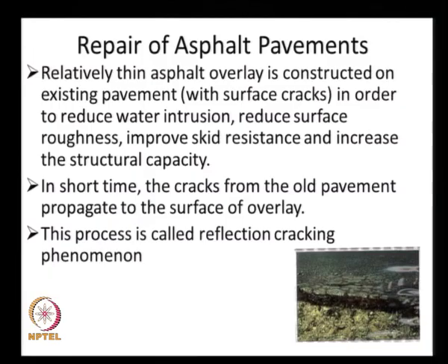And when we are repairing, sometimes these old cracks may be filled or may not be filled, and sometimes we notice that within a short time the cracks from the old pavement propagate to the surface, and the new pavement also undergoes failure.